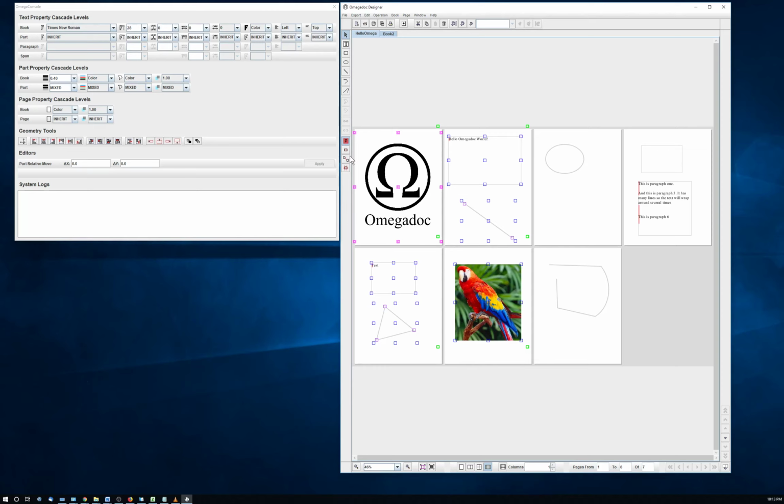The double box magenta indicates an active selection within this overall selection. The remaining selections with the blue boxes are just regular selections. I can change the active selection by pressing the page up or page down. I'm pressing the page up key now, keyboard key, and you can see that we're cycling through the active selection.